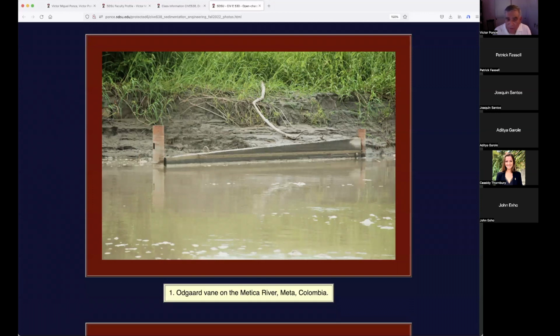They're hammered into the river at certain locations in certain quantity. I believe in these projects, usually they have 80 or 100 of these vanes in a certain location. The objective is to avoid having the river meander. Now, obviously, that's a losing game because the river is going to meander no matter what. So what our friend Carlos has done in here is stop the process temporarily. Temporarily means, if he's lucky, 5 to 10 years, maybe 20. But he cannot stop it forever. Forever is a very strong word. Forever would be like 5 generations down the road. God knows what could happen. What could happen?